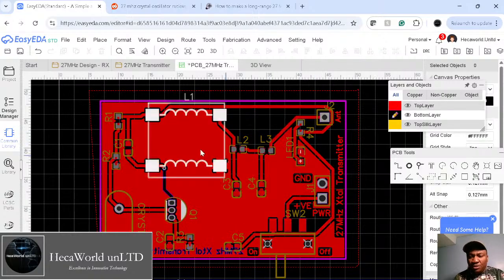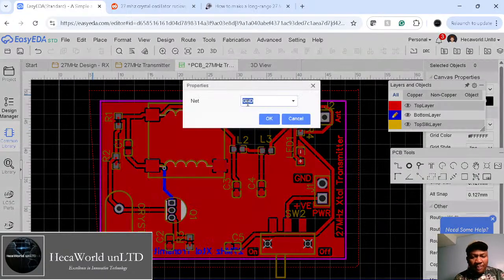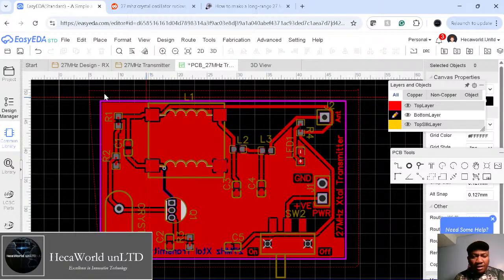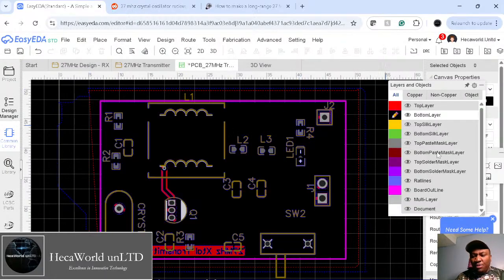When we do the bottom of the board, E, press OK. If I click on here and I go there, click, go down here, click, go right here, click. It doesn't know that I've done 4 corners or 5 corners or 150 corners. It just keeps waiting for me. I think if you double click, it will still be dragging. So escape, and then it will apply.